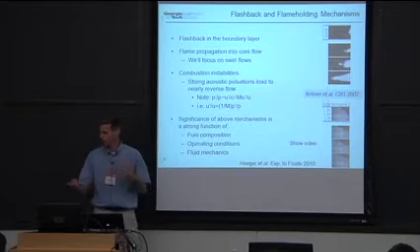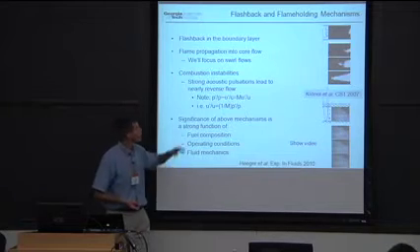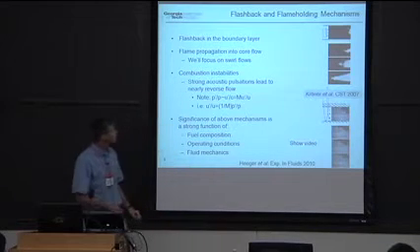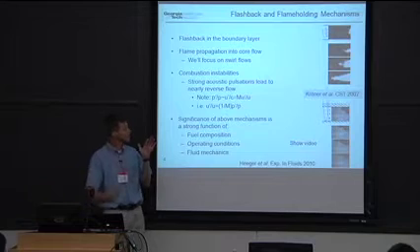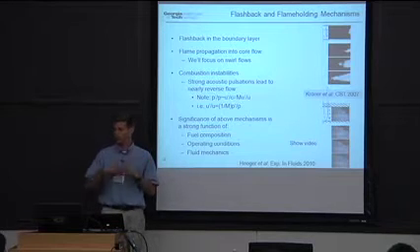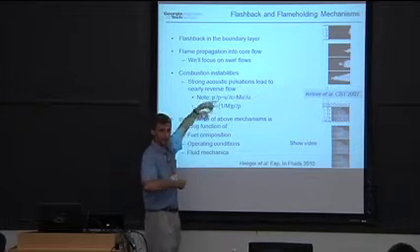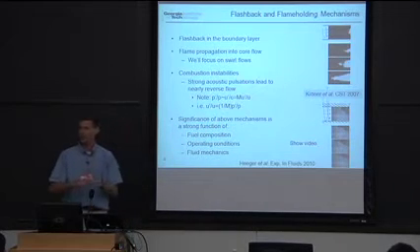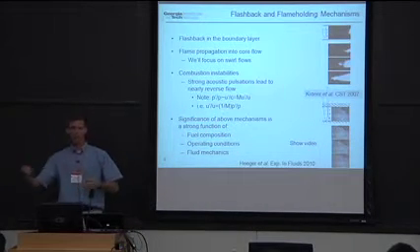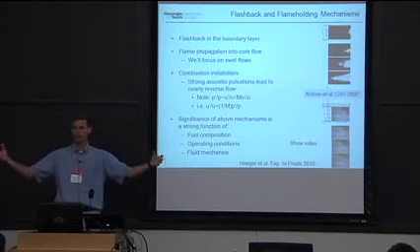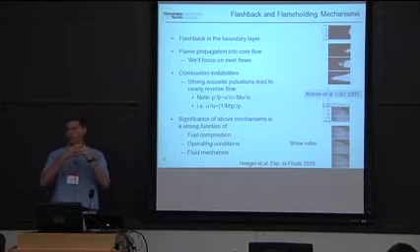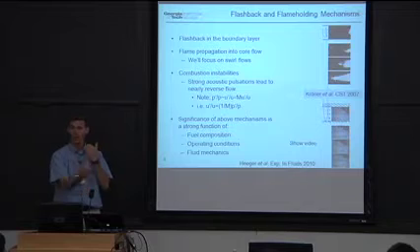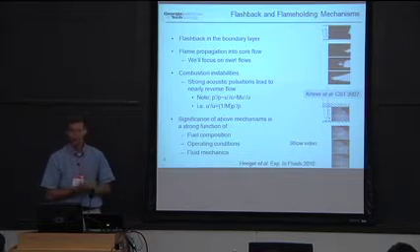If that's not the case, then the flashback mechanism is kind of trivial. If you have a low velocity region, the flame can shoot up. But I want to show you that there are some non-trivial mechanisms whereby flames can shoot up in the core flow when you have swirl. When the flow is spinning, the flame starts to interact with the hydrodynamic stability of the flow, and it creates a mechanism. If it's just the flame or just the flow, nothing can happen. But the two come together and create additional physics, and the flame can shoot upstream in the core flow.